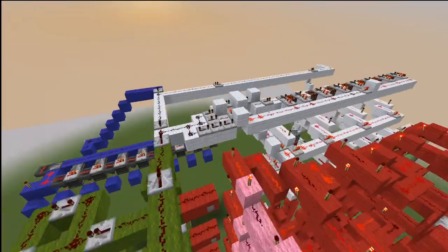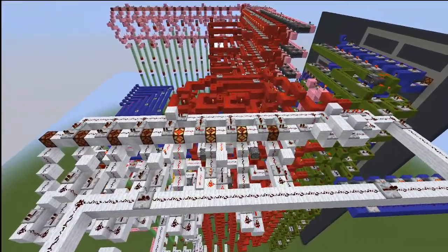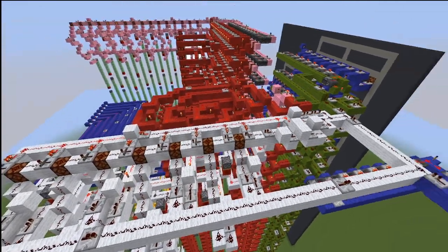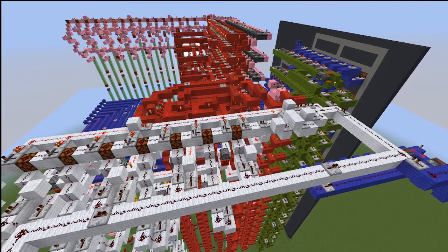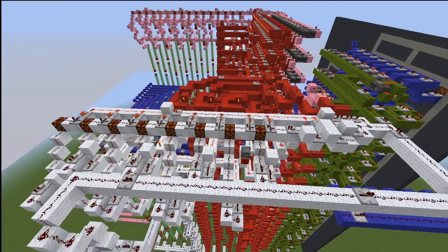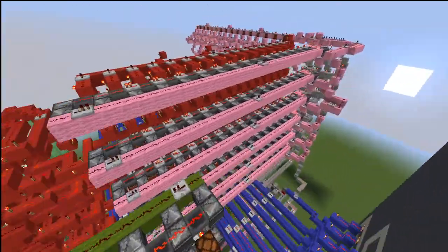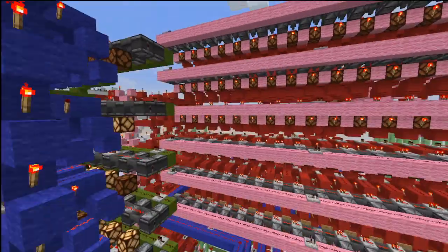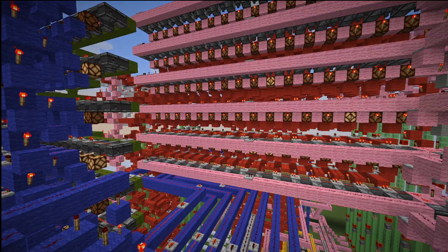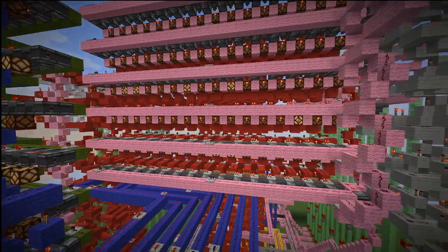So it's going to read what's in the program counter, which we can watch. Right now there's a 0 in the program counter. And so it updated to a 0, and then it's going to read from the memory address register location 0, which is also going to be a 0. So it's going to update again, and we'll have another 0. Okay, and now we get to watch the instruction register change to include the instruction set for clear. And there it goes. It just updated the instructions.